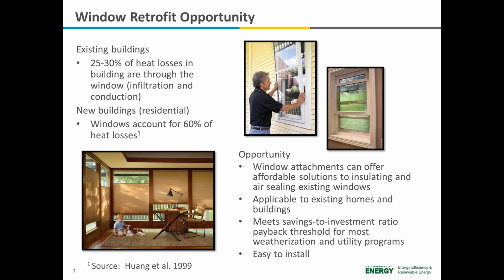Not only can they reduce the energy consumption in the building, but what we're finding is they can do it in an affordable manner. Often window attachments will meet the savings to investment ratios and payback thresholds for a lot of the different weatherization and utility programs that are out there. They can be applied to existing homes, and they can be easy to install, so a lower installation cost. And I don't have it listed here, but equally important, they can add to the comfort of a home and the aesthetics.